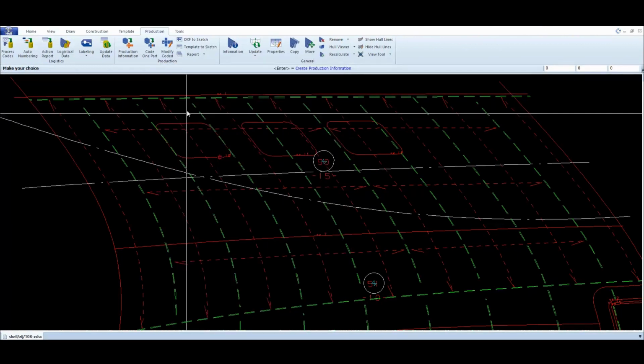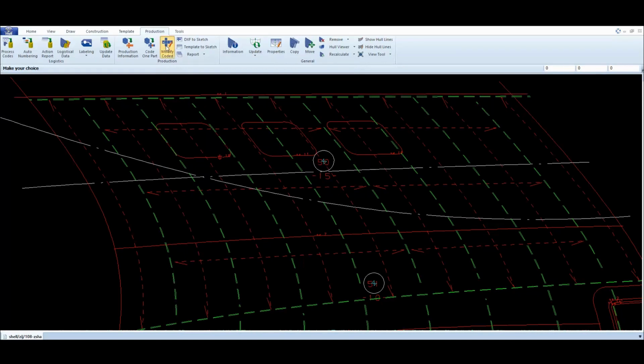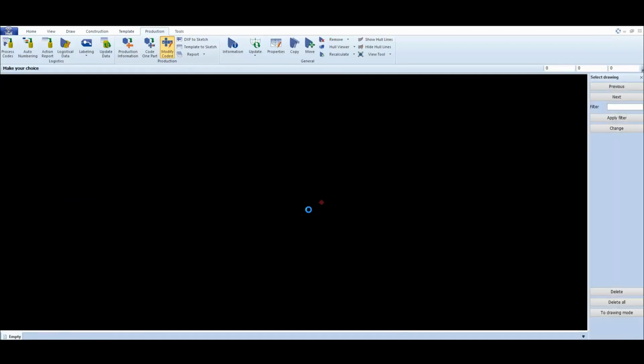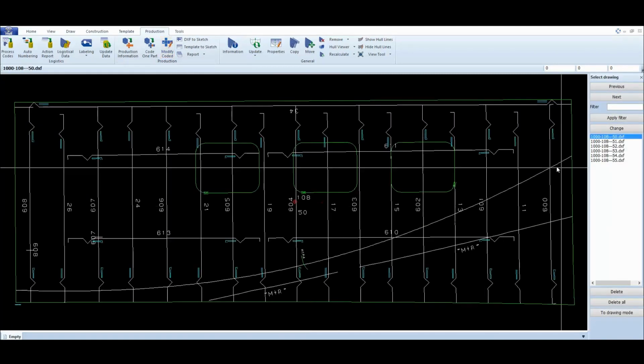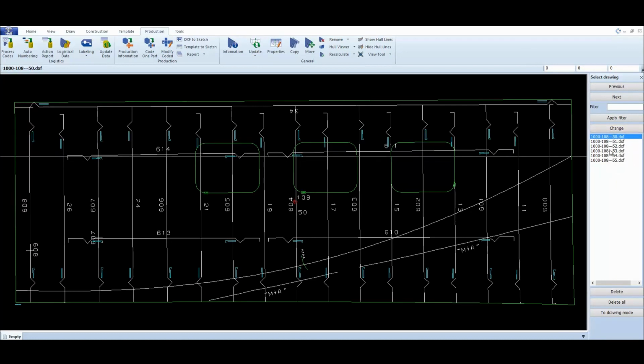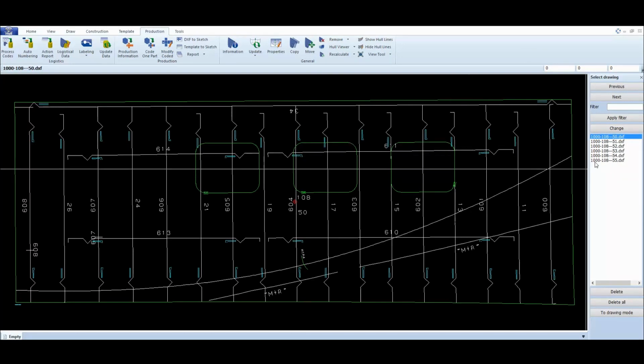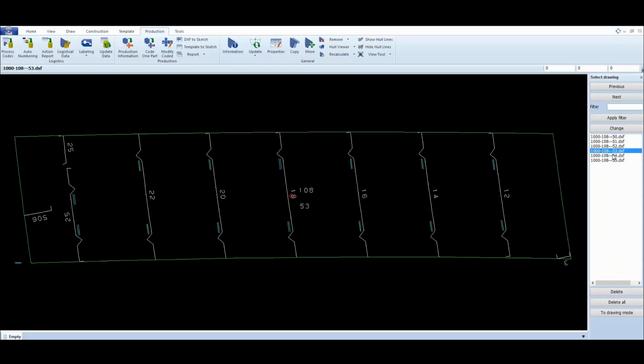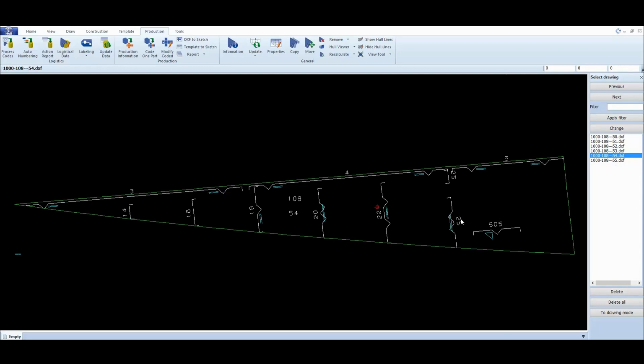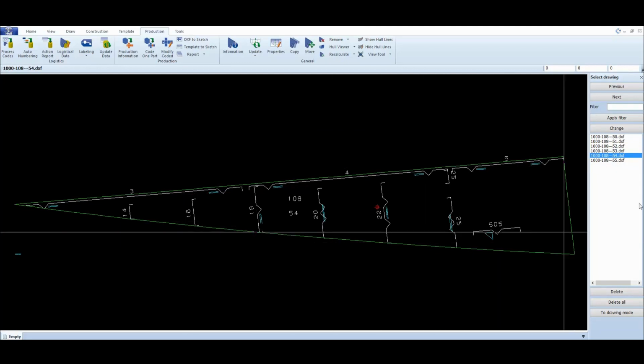In order to inspect the generated DXF files, we will go to the function. Yes, we do want to save our view. And we will see here a list with the DXF files for all the shell plates. And having part numbers for shell plates is very useful because it's also used here in the name. This name can be customized. Okay, so we have very nice DXF files for all of the shell plates. Look also for the triangular one.